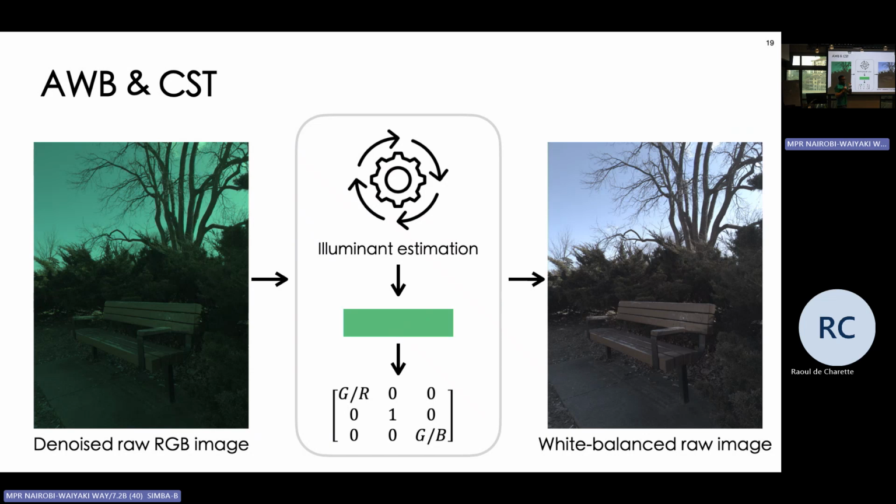And for what you are saying, this is maybe a specific use case of the camera ISP, where you can customize your camera ISP to improve the visibility of dark regions, for example. But I don't think this is related to white balance. White balance just adjusts the chroma values, not the intensity. But we can do that in later steps I will discuss, okay? Okay.